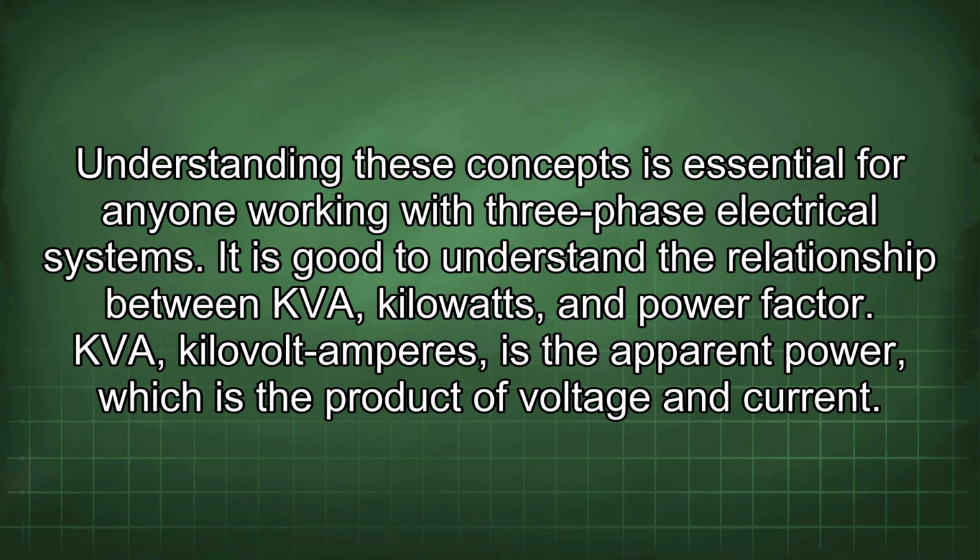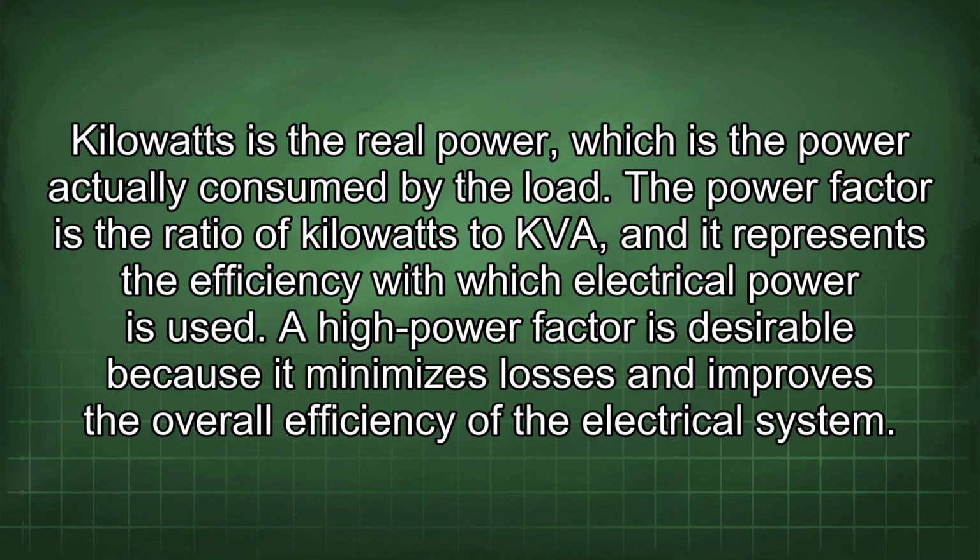It is good to understand the relationship between KVA, kilowatts, and power factor. KVA, kilovolt amperes, is the apparent power, which is the product of voltage and current. Kilowatts is the real power, which is the power actually consumed by the load. The power factor is the ratio of kilowatts to KVA, and it represents the efficiency with which electrical power is used. A high power factor is desirable because it minimizes losses and improves the overall efficiency of the electrical system.